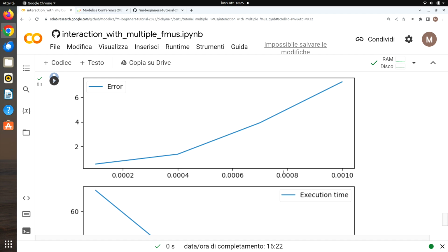And by the way, your question about determining this offline: the order tells you the shape of this convergence function. It doesn't tell you the exact values. So if you've got an order of accuracy of the third power, then that curve will be sharply towards the origin, which indicates you are going to nicely, quickly find a good step size that's large enough. But if the order is linear, then it's going to be a painful process. Then you have to run your detailed simulation one time. You have to accept this fact.